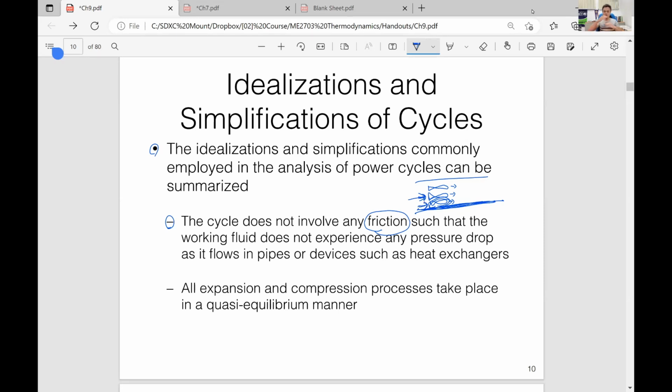Okay, so that is the layer by layer concept. That's why when a flow is flowing through a pipe, there will be a pressure drop, and this pressure drop comes from the viscous effect. Okay, and we know pressure is actually energy per unit volume. So when pressure drops, that means energy drops. Okay, so this is the idea.